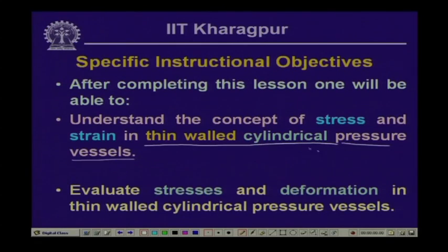Now, here we are concerned with two aspects. One is that the vessel is subjected to internal pressure, and this internal pressure is over and above the external pressure. By overcoming the external pressure on the vessel, the internal pressure is working, and thereby there will be stresses generated in the vessel, and we are interested in evaluating those stresses.